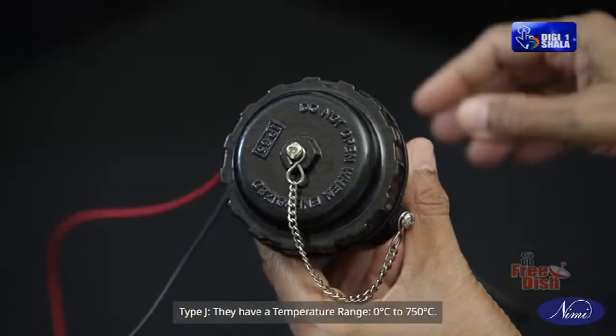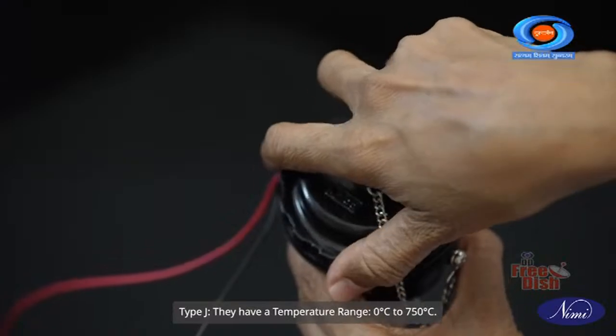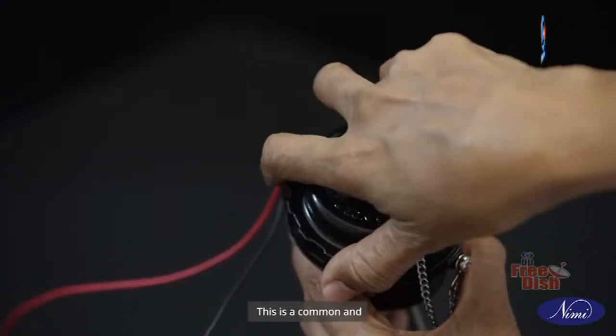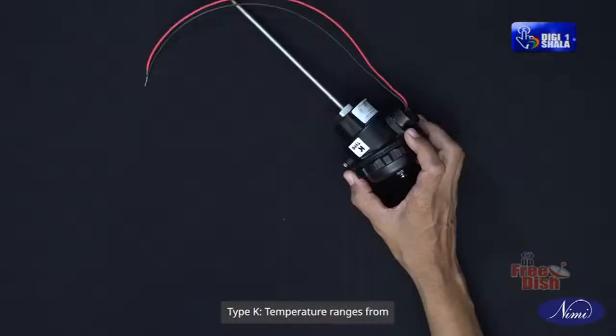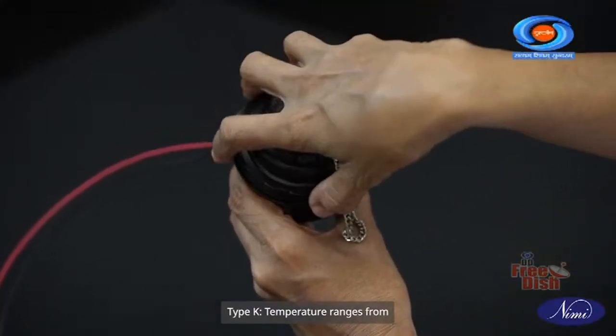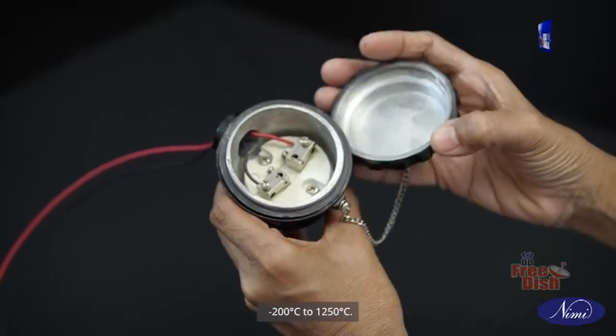Type J, they have a temperature range from 0 degrees Celsius to 750 degrees Celsius. This is a common and cost-effective option, but not ideal for high temperatures. Type K, temperature ranges from -200 degrees Celsius to 1250 degrees Celsius.